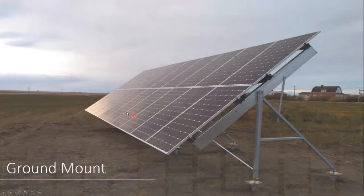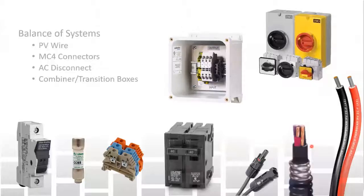Also, these mounts work with 60 and 72 cells like the rest of the racking systems, and I can either do long linear runs, or if I have the room, I can space these out one in front of the other. Just make sure the spacing maintains the correct distance so you avoid shading. So ground mounts are a great option. You can also get into some tracking systems more commonly used in commercial. 3-axis was popular for a little bit. Now you'll see 2-axis that just follows the sunset, sunrise.